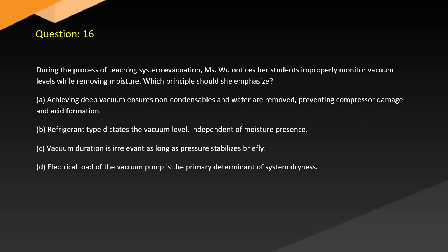Question 16. During the process of teaching system evacuation, Iswu notices her students improperly monitor vacuum levels while removing moisture. Which principle should she emphasize? A. Achieving deep vacuum ensures non-condensables and water are removed, preventing compressor damage and acid formation.